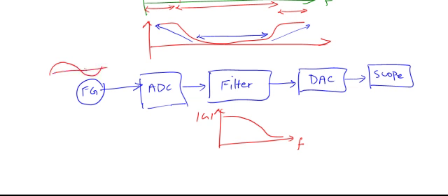What I expect to see, if the filter is a low pass filter designed by the FDA tool, is this. We are going to use the FDA tool to design the filter. So if a low pass filter is designed, when I increase the frequency on the function generator, and of course there's a knob on the function generator that you can use to increase the frequency, I should see a lower and lower amplitude.